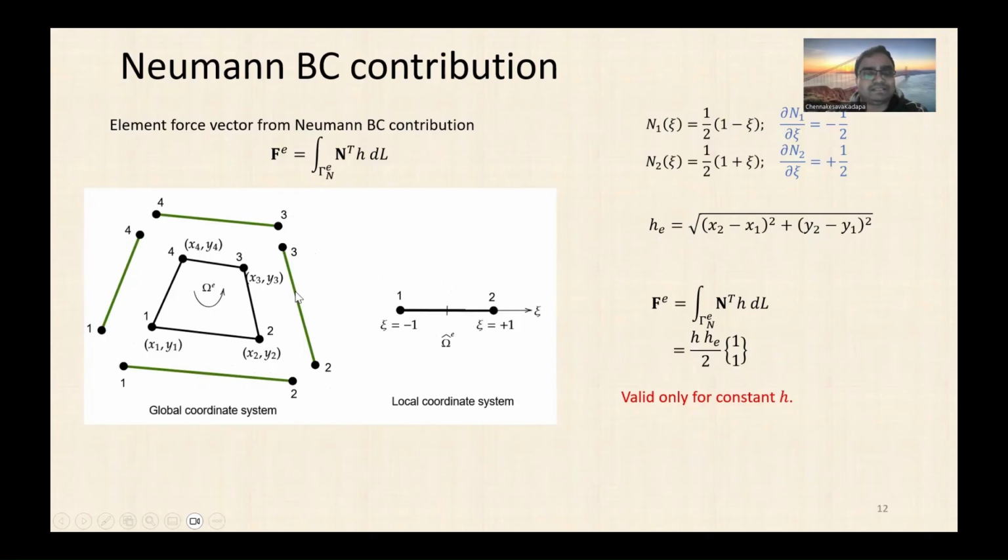Okay, the difference is that in the physical domain, the 2-noded element can have coordinates both x and y non-zero. Okay, we map that to a 1D element with only one coordinate, right? Only xi. So there is some slight complexity that we need to deal with. The complexity is in creating the mapping and the Jacobian.